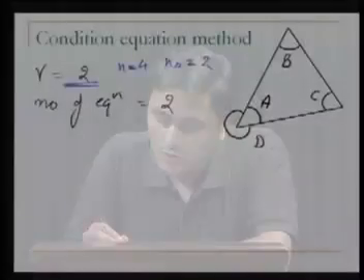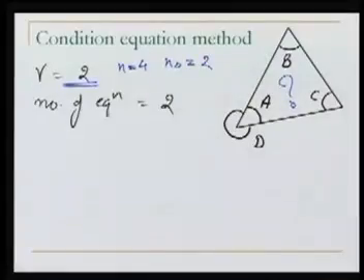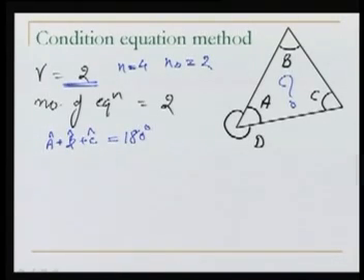So we'll look into our system of observations and what is desired. Is there any geometric condition? Is there an observation condition? So we need to look into that and we need to find those conditions. Well, the very first condition we can write as A hat plus B hat plus C hat. This should be equal to 180.